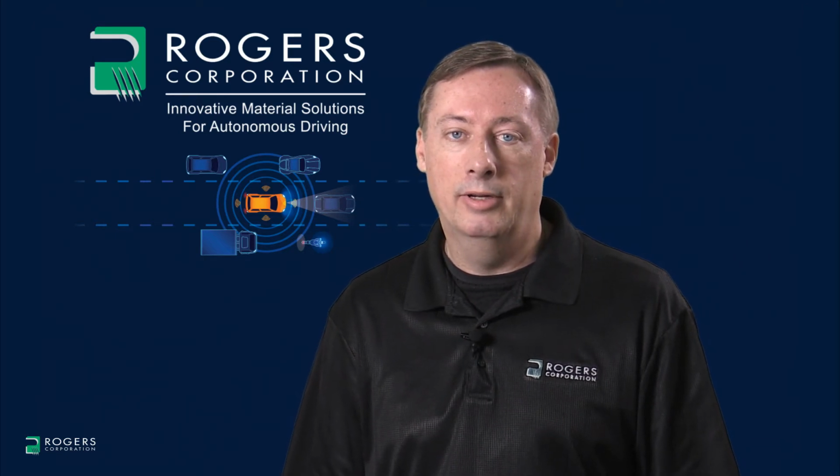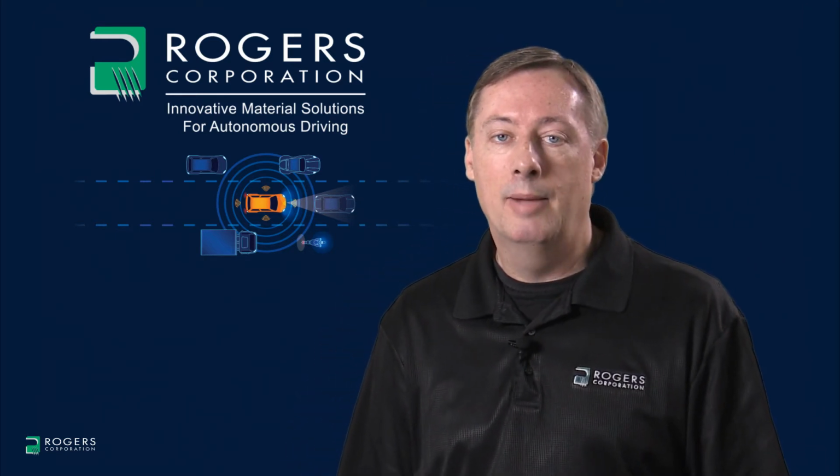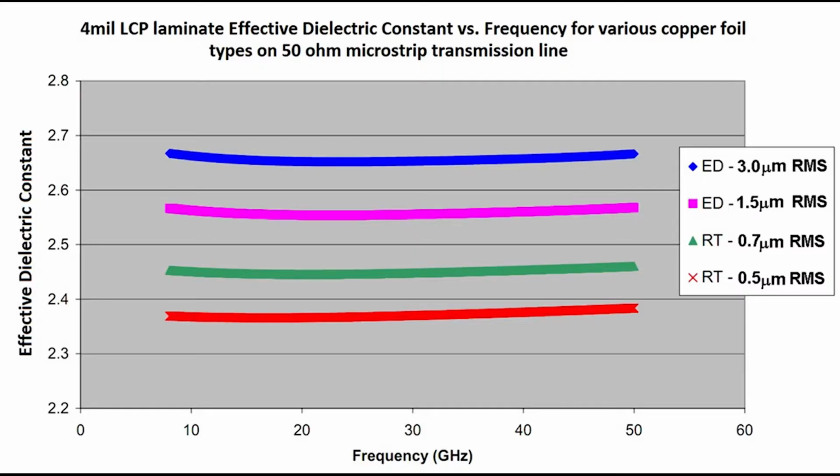What we found is there are more things than just the substrate dielectric constant that can slow the wave down, and copper surface roughness is one of those. Shown here is an excerpt from one of our studies looking at copper surface roughness. We built four different laminates using 4 mil LCP. We used the exact same substrate, but four different types of copper that had significantly different surface roughness. We first tested the copper with a non-contact laser profilometer to understand what the surface roughness really was.